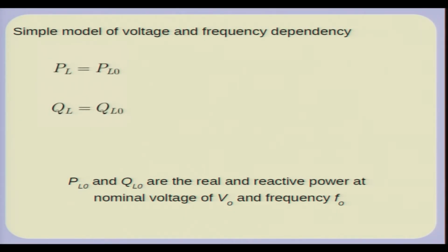normally we can characterize a load by how much real and reactive power it draws. One could think of representing a load as an impedance, but not all loads are in fact what you call constant impedance type. One of the ways of representing a load is to have a simple linear dependence on the voltage and the frequency. Linearity, of course, will exist only if there are small changes. So, this is an approximate representation of load.